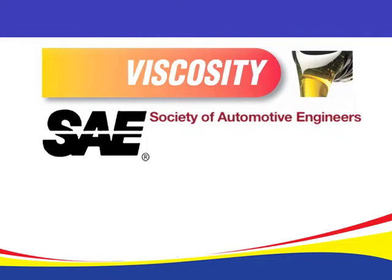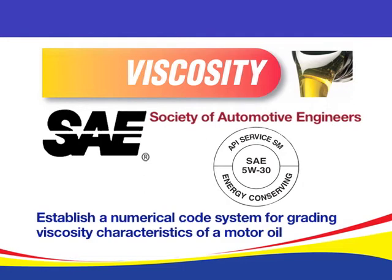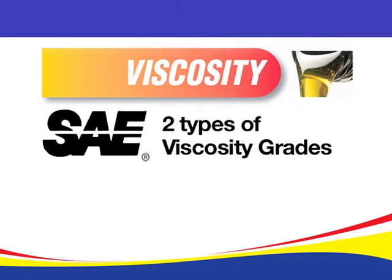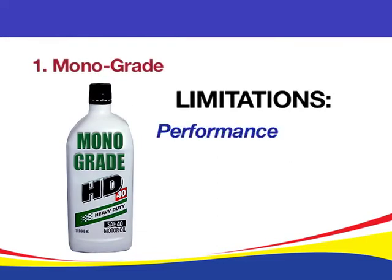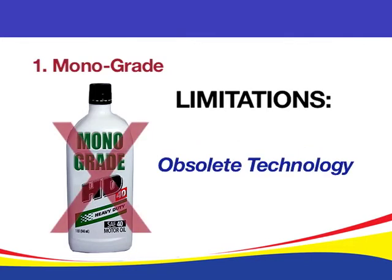SAE, the Society of Automotive Engineers, has established a numerical code system for grading motor oils according to their viscosity characteristics. If you see this seal on your motor oil bottle, it represents that the viscosity of the product has been approved by the SAE. An important point to understand is that there are two types of SAE viscosity grades, mono and multi-grade motor oils. Mono-grade motor oils have limitations in performance and operating conditions. Also, it is considered an obsolete technology.